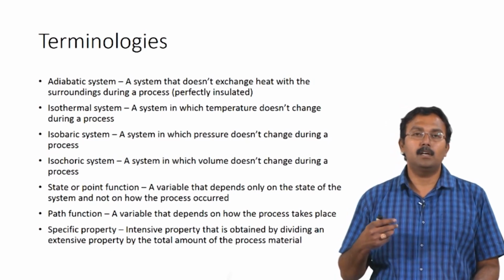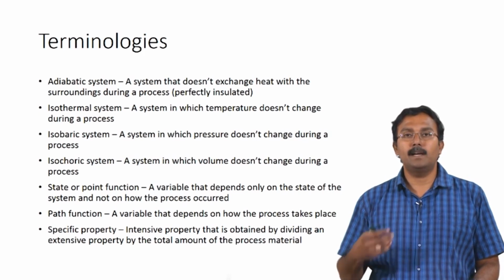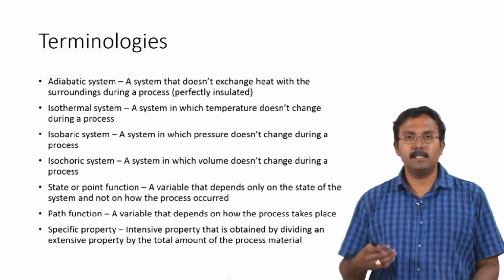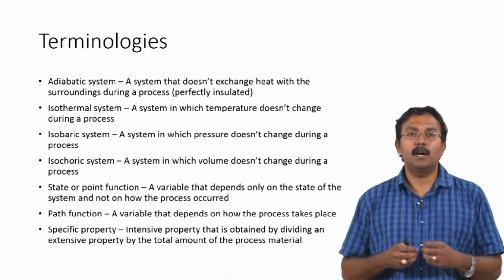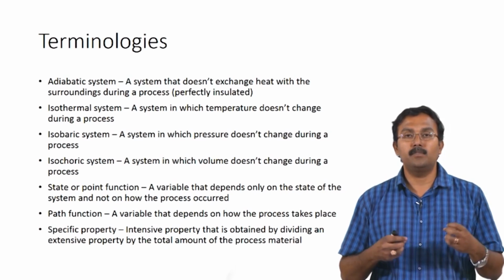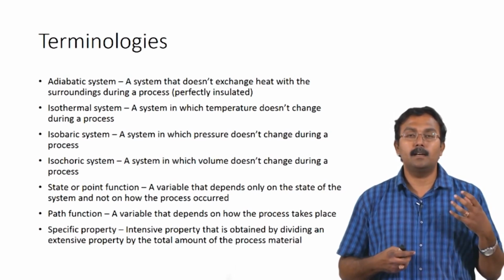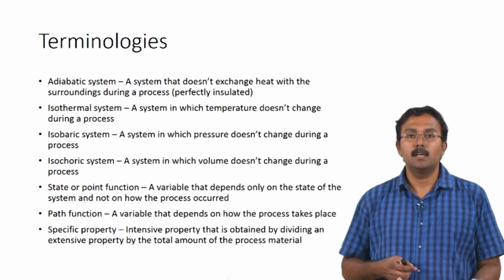Depending on whether a closed system is isobaric or isochoric, you would have to identify the appropriate energy balance equation which you will use. Please refer to the previous lectures to identify why we use internal energy for isochoric systems and enthalpy for isobaric systems while we perform calculations.